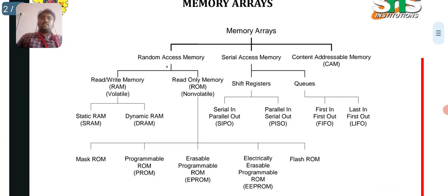Array architecture in the context of memory circuits refers to the way memory cells are organized and accessed within a memory array. This structure is essential for efficiently storing and retrieving data in various types of memory, including SRAM, that is static RAM, dynamic RAM, ROM, read-only memory, and flash memory. The design of array architecture influences the performance, power consumption, area, and overall efficiency of memory circuits.